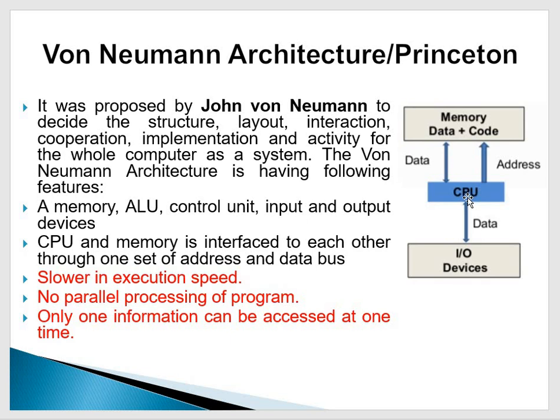During the execution of the instructions, whatever command it fetches from the memory, data will be required. So another essential part of the memory is called the data memory. So at least two types of memories are required which have to be interfaced with the CPU. And as we already discussed during the discussion of the data structure, minimum three types of buses are required to interface any external device, either memory or IO device.